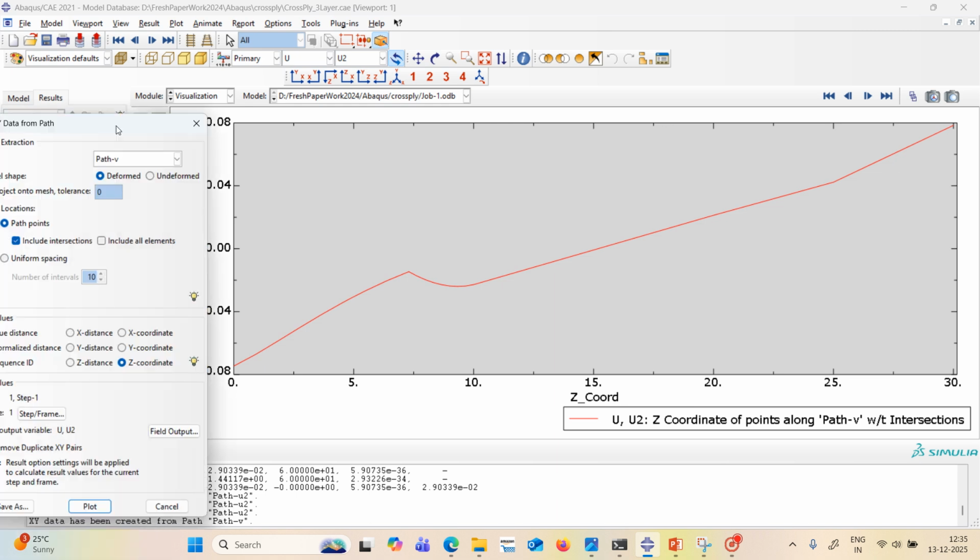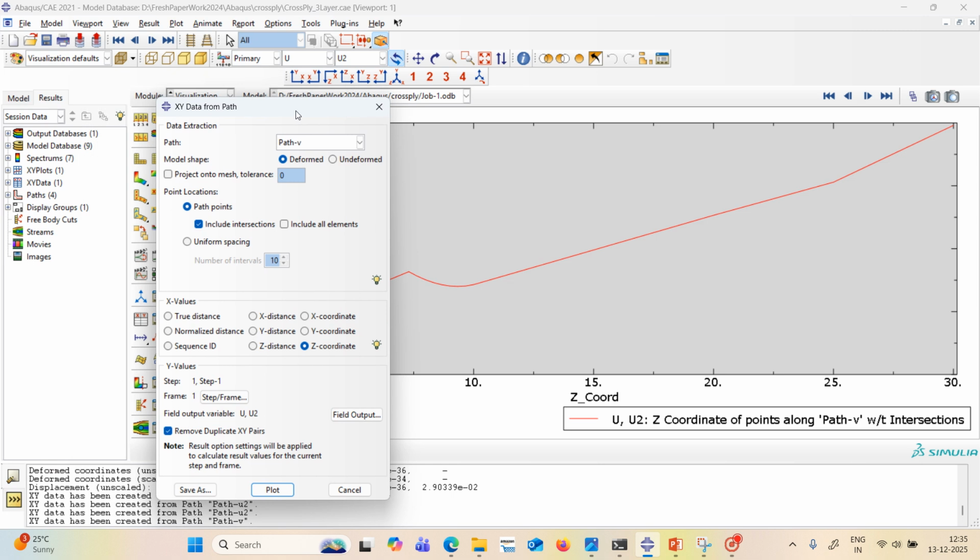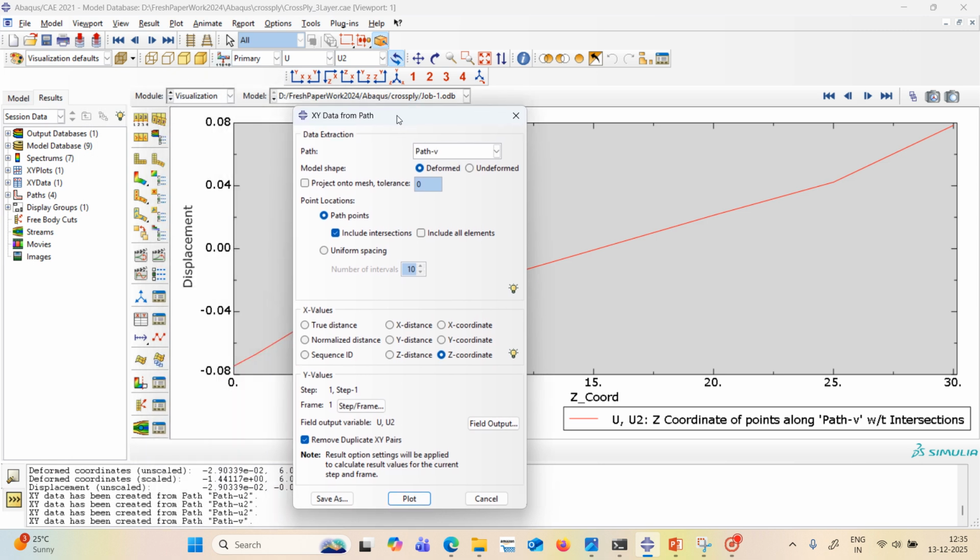So this is a very coarse mesh. If you want better results, we have to refine it. Once we refine the mesh, we get better results. Fineness is compulsory for any FEA analysis. So we start with the coarse one. Once we see we are getting a good structure and good results, then we refine the mesh and get the convergence of the results.